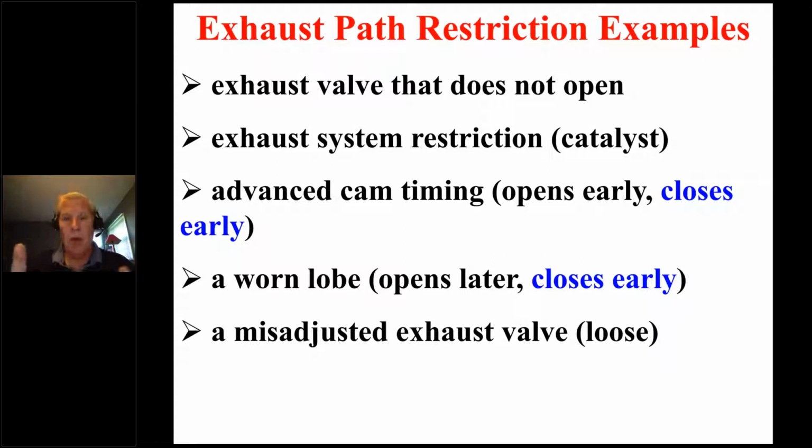Now the next few I group together. While they're not necessarily the same thing, I group them together. And here's what I'm getting at. We've kind of discussed this, so this is nothing new here. If a cam, whether it's one cam or double overhead cam, exhaust cam, if the cam timing is advanced, everything occurs earlier. Valves open earlier, valves close earlier. So you'll notice I've highlighted in blue, closes earlier, because that's what I'm interested in right now. So if the piston is coming up on that exhaust stroke and that exhaust valve closes too soon, we trap air and we have the pressure pulse.